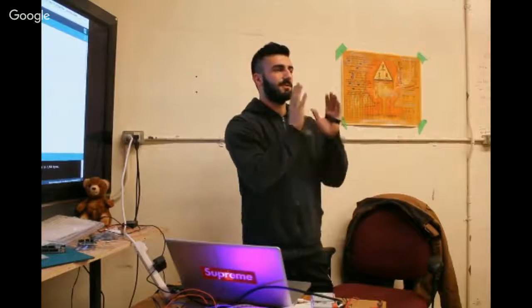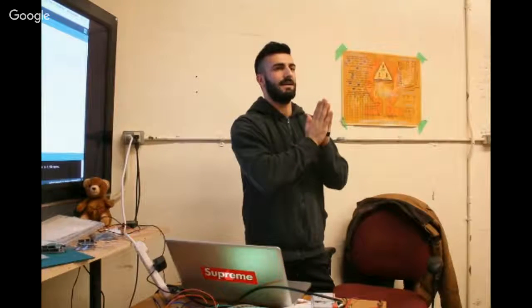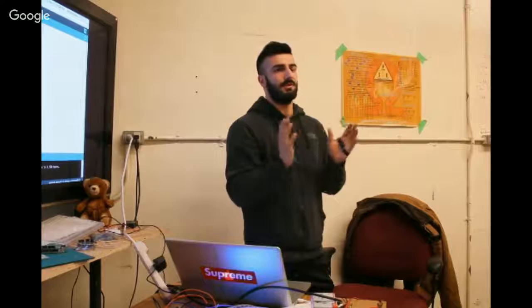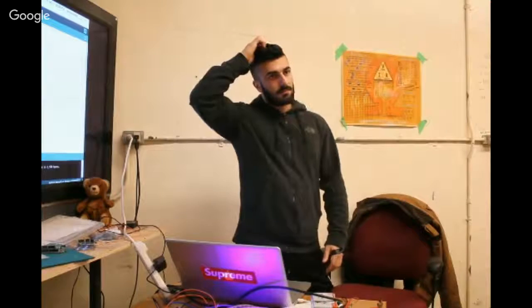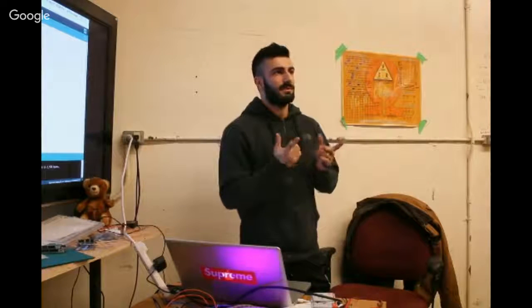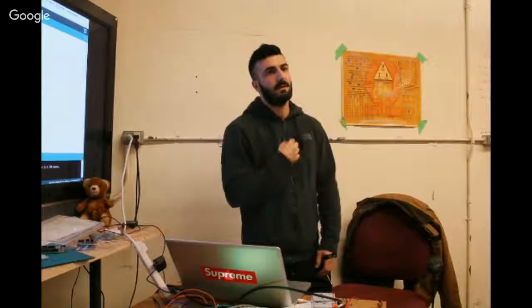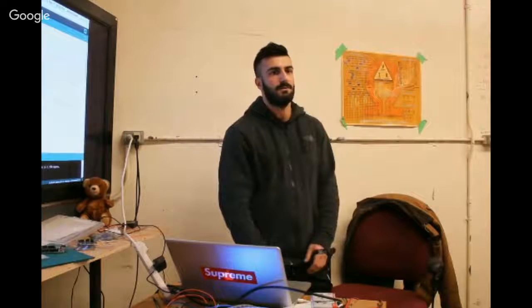So basically it's open, which means there's no electricity running through the AC side. Once we put 5 volts DC onto the relay, that will close the circuit, which will turn on the motor. So basically, it's a switch that we can control with 5 volts DC. So that relay specifically responds to 5 volts DC, or can it be any? There's a range on it, so it depends on which one you buy. The one that we have in there ranges from 3 to 24 volts DC. Okay, and that will cause the switch to close. Yeah, exactly. So anything outside of that range will not respond. Okay. And then it completes the circuit.